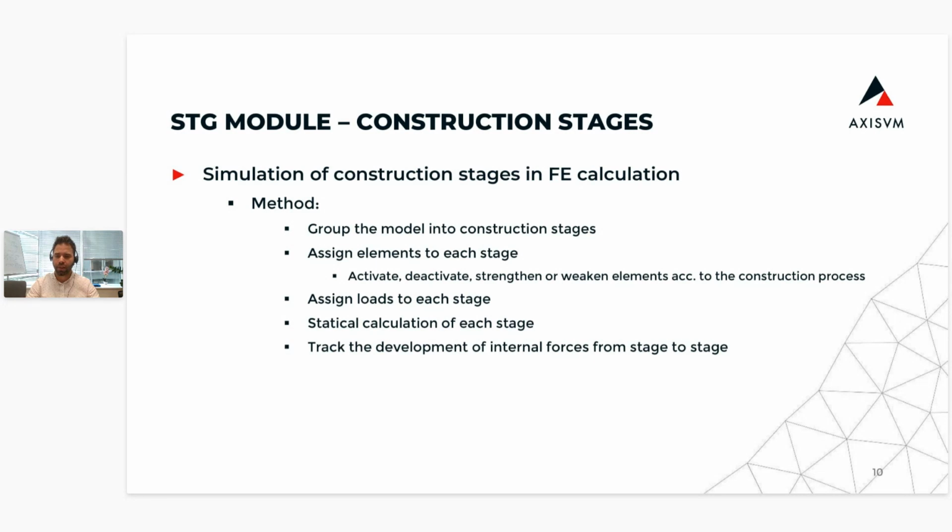And we not only need to assign elements to these stages, but we need to assign loads as well. So we will assign loads to construction stages, acting in that specific stage. And after that, we will perform a static calculation for each of the stages. And by evaluating the results for each stage, we can track the development of internal forces from stage to stage.